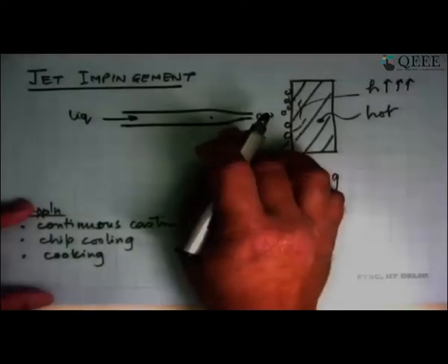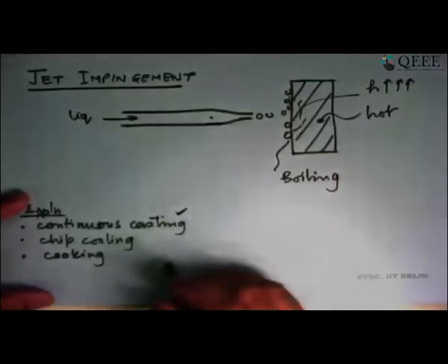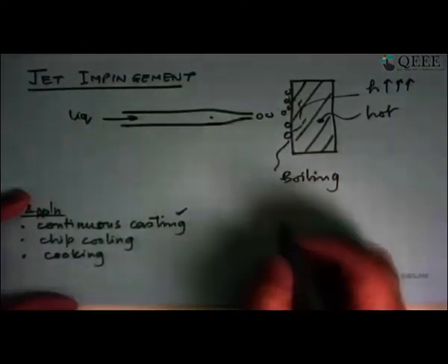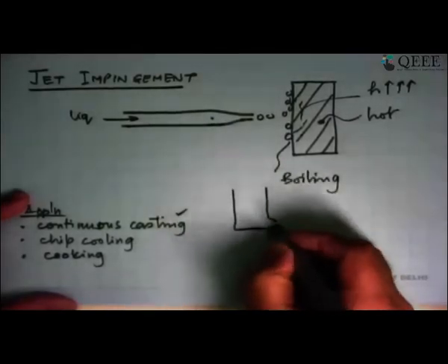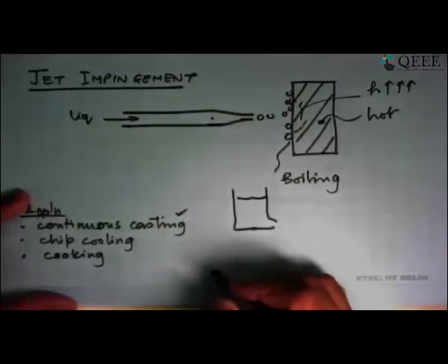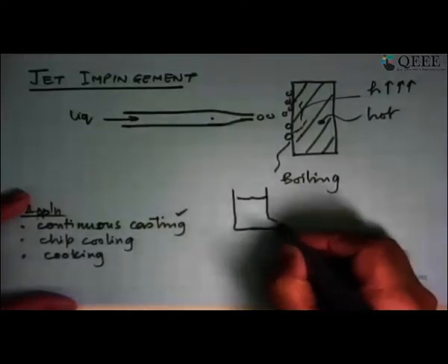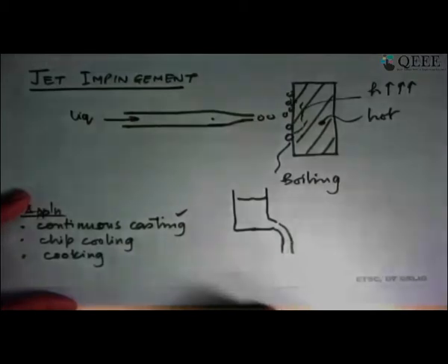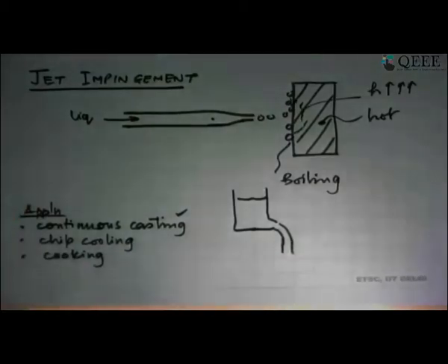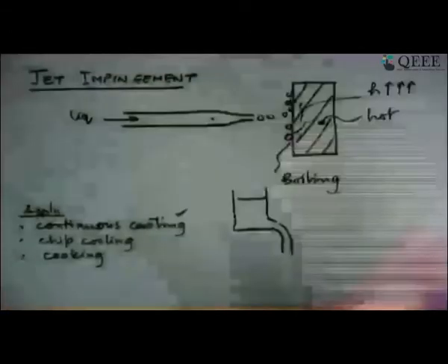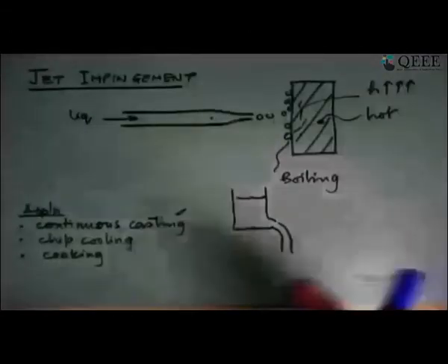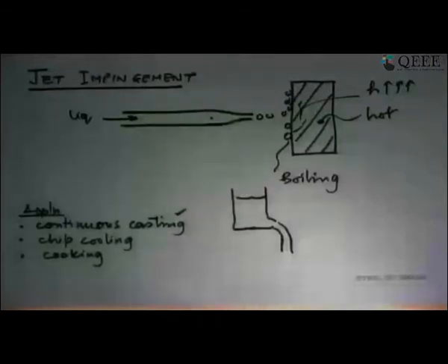A real big example of this was in continuous casting. And what happens here, if you have learned in any of your manufacturing courses, is that we put liquid metal here, it could be say steel, and from there this liquid metal drops down. And the traditional idea is that we take this liquid metal, put it in the mold, make it into a solid slab, and then we take that slab away, take it into a furnace, again heat it up, then you put it into a rolling mill and start making shapes out of that.